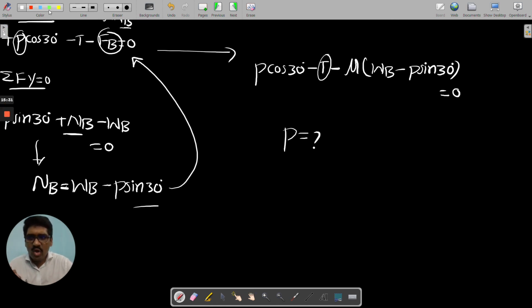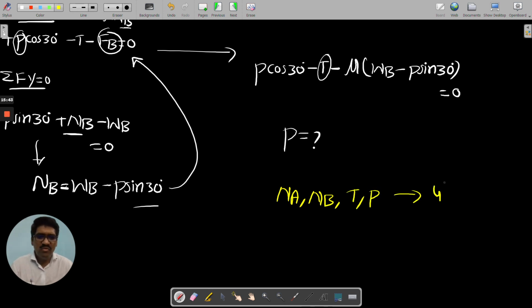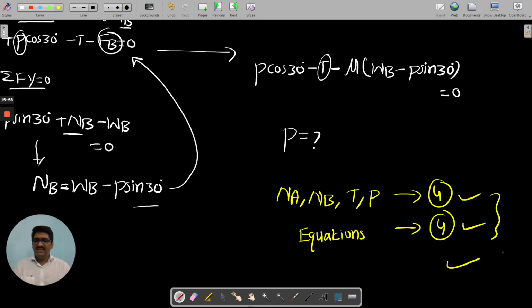The total number of unknowns in the problem are NA, next NB, next tension T, next P. Total number of unknowns are 4. Total number of equations of equilibrium are also 4. Therefore, 4 unknowns and 4 equations, definitely you can get the answer here.